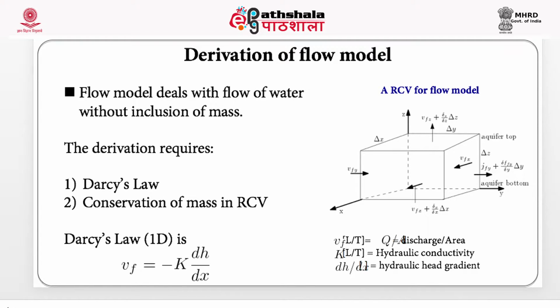Now to derive a flow model, we require two fundamental groundwater or physical principles. The first one is the Darcy law, and the second one is conservation of mass in the RCV, our model aquifer.